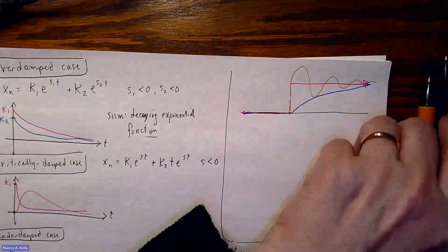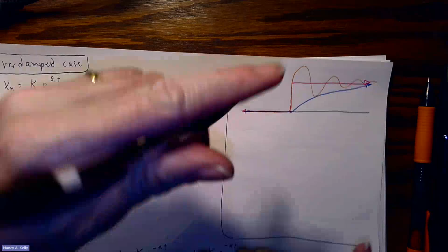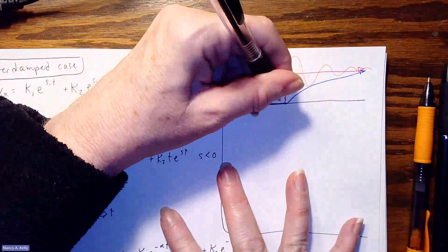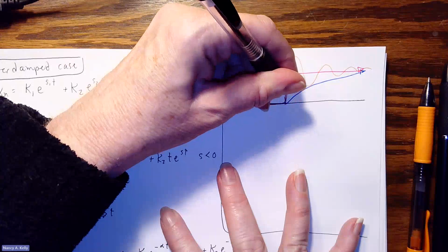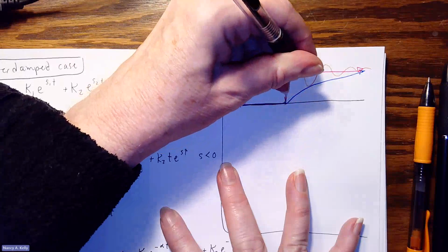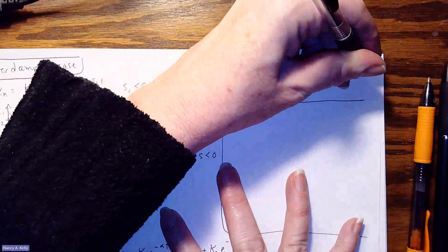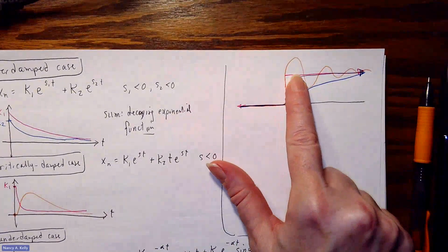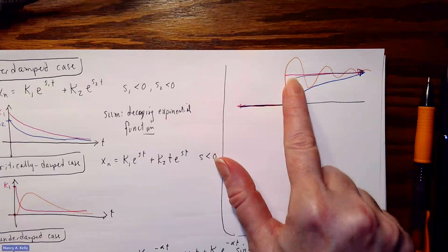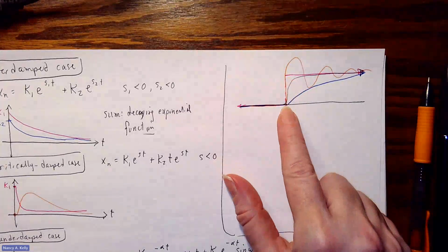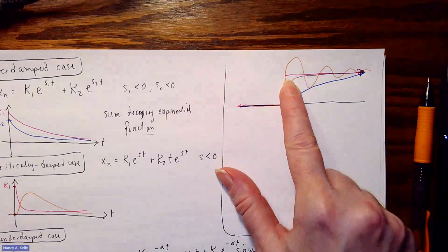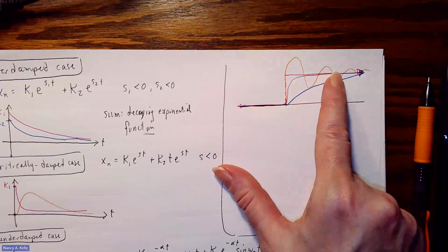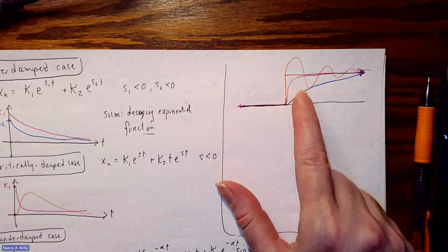Okay, and then critically damped is kind of like the Goldilocks, just right, you know. You just go up here and you get something that's more like this. Okay, it's very hard to hit that critically damped case. It's not going to go up immediately at the target time, right? It's going to also need a little bit of time, but it probably isn't going to overshoot, right? It's going to go up to where it's supposed to go. It takes a little bit more time.